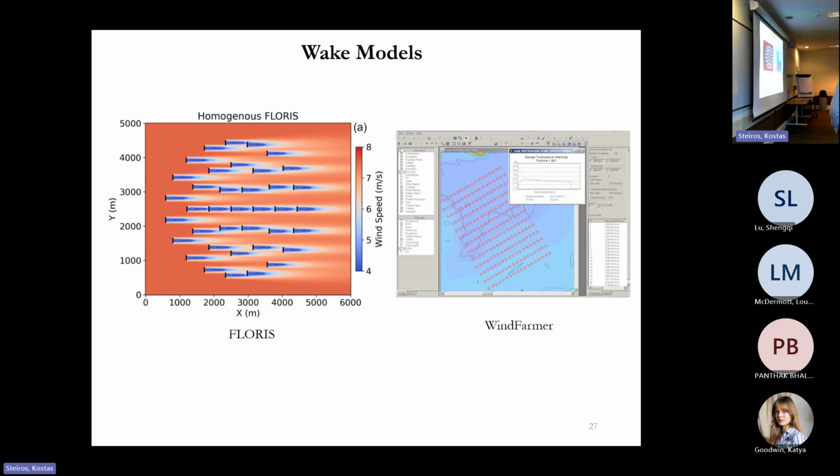So here I plot a contour plot of the free stream velocity, of the wind speed. And you can see these are wind turbines here in the wind farm from above, it's a simulation in a sense. And the flow flows from left to right. Downstream of the wind turbine, we have a low velocity region. So it's very bad if a wind turbine is directly behind the wake of a preceding one, right? We lower a lot its acquired power.